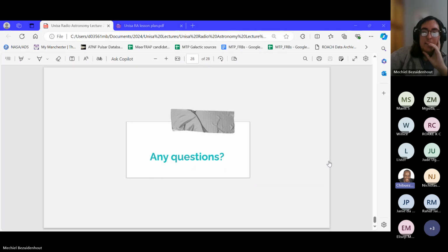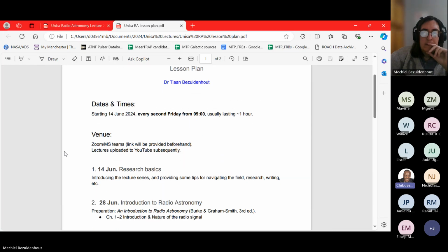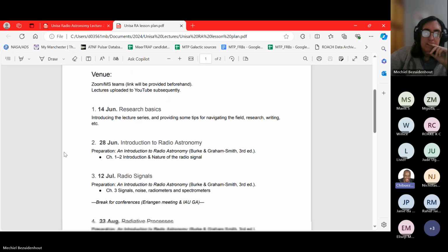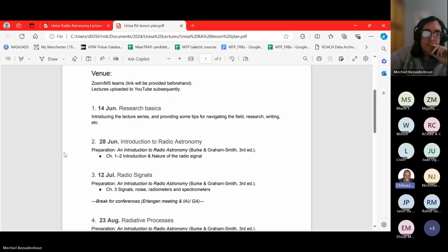So essentially, what you do in the correlator is that the two antennas are separated by a certain distance. It doesn't matter how small, even if it's just 10 meters apart, the time of arrival of the signal from a source to each of the two antennas will be different. So at the correlation stage, you're essentially removing the time delay and then combining the data.